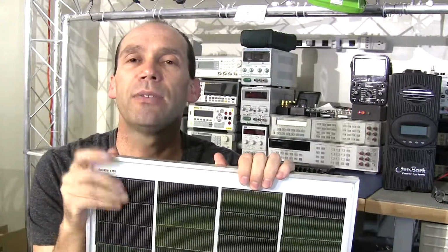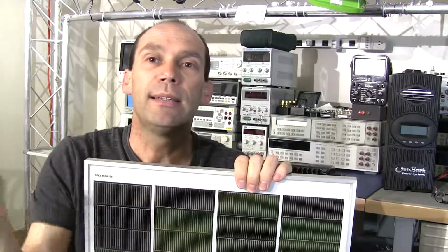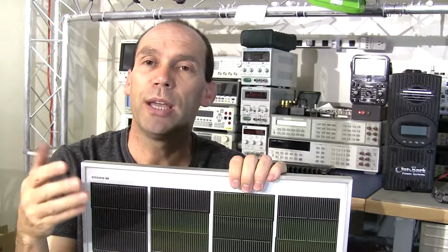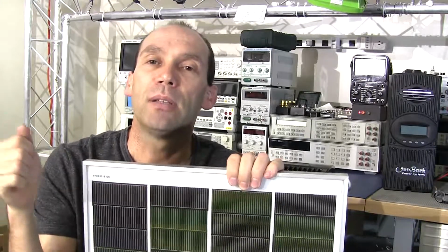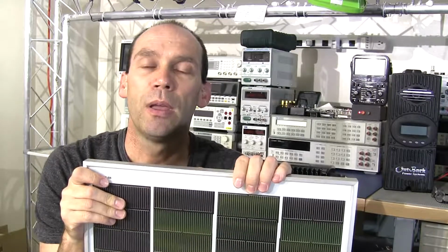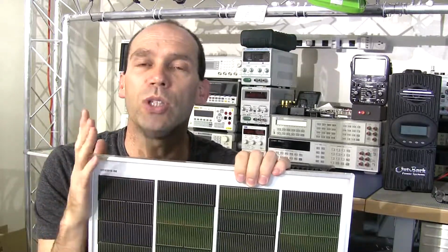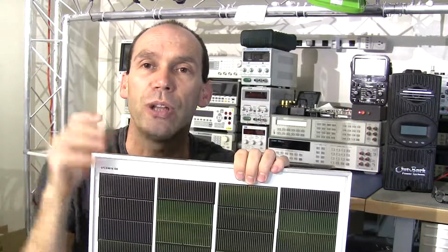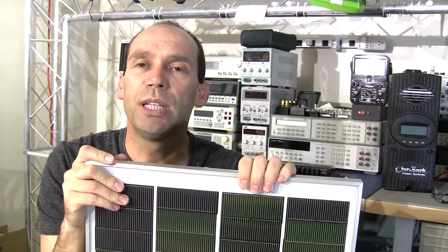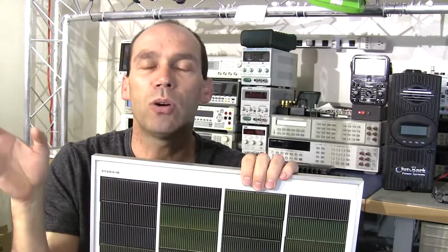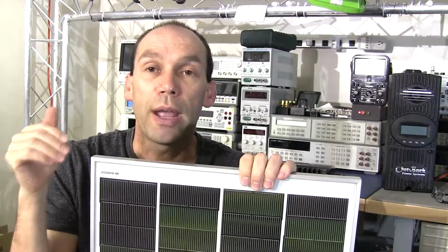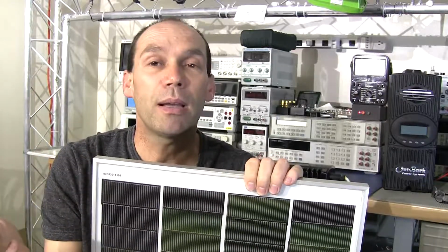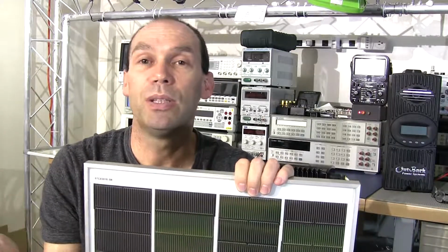Now when I say that, it sounds very easy. With the old DC systems, or let's say the charge controllers, you had to be very wary of having proper switch gear, DC breakers, and ways to switch off the power in an emergency. Those things do become simpler once you have your microinverters, or even integrated AC power production directly from the solar panel. But you still need to be aware of the safety coming into your breaker box, your DB board, and then also going out onto the grid, and the implications of doing that with your own power company. Some power companies allow that, some power companies don't.